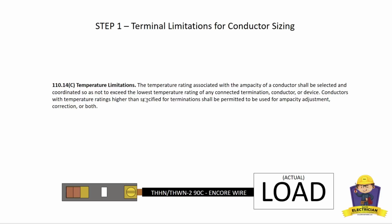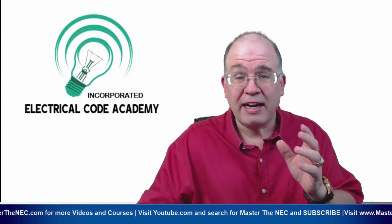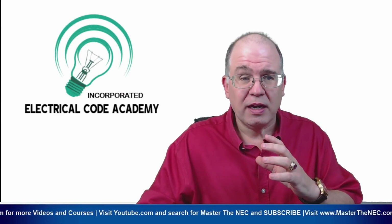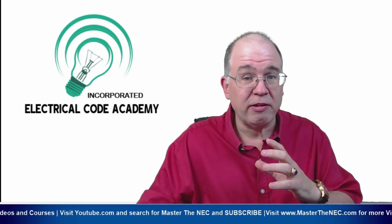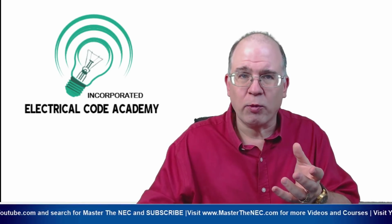110.14(C) is a temperature limitation. It states that the temperature ratings associated with an ampacity of a conductor shall be selected and coordinated so as not to exceed the lowest temperature rating of any connected termination, conductor, or device. Conductors with a higher temperature rating than specified for terminations shall be permitted to be used for ampacity adjustment and corrections, or both. So what we're saying here is we're going to let you use a 90°C rated insulation, for example, for derating or ampacity adjustment and corrections, as long as you follow the requirements of 110.14(C).